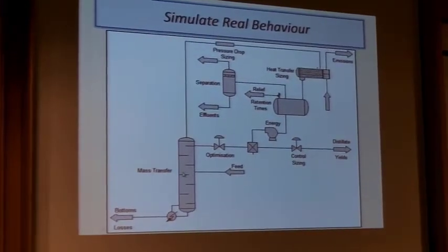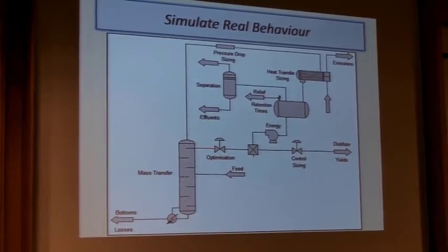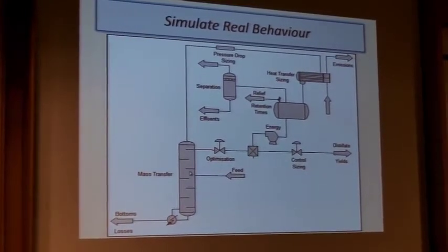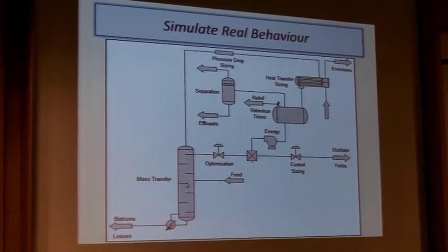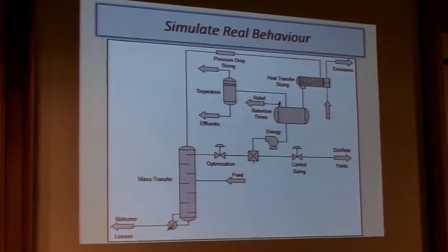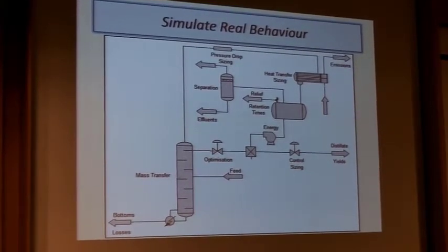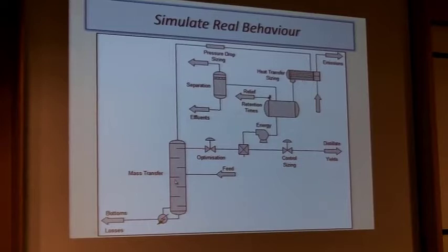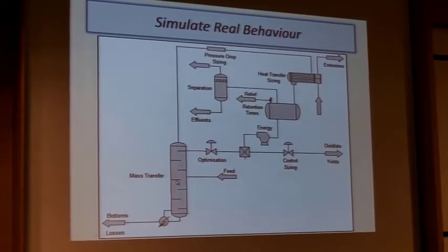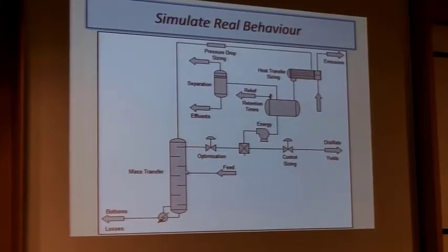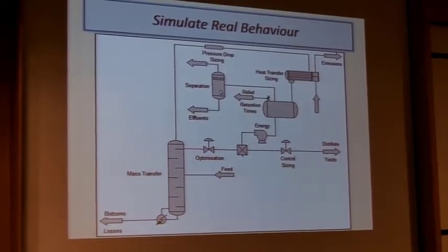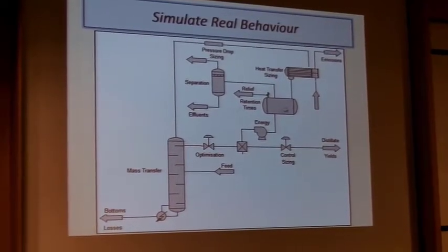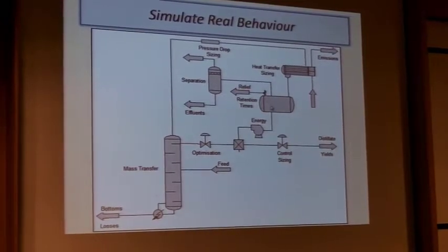The simulator is graphical based, and what you basically do is take from a palette various unit operations which hold the mathematics associated with a particular operation. So there's a distillation column, which has all kinds of algorithms in there to study distillation, reactive distillation, simple vapor liquid equilibrium. You've got flash vessels, which can do flashing of liquids. You've got simple dynamic vessels. You've got relief valves.